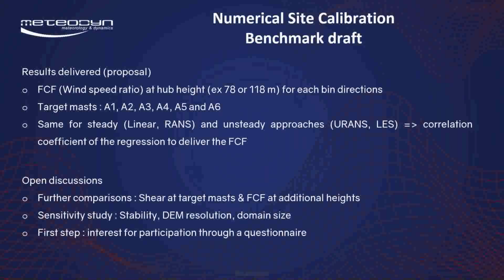Moreover, we will carry out some sensitivity study by changing the stability. So we have 3 stabilities, and by changing also the digital elevation model resolution, because this is a parameter that gives some uncertainties, and also we can test the sensitivity of results to domain size.